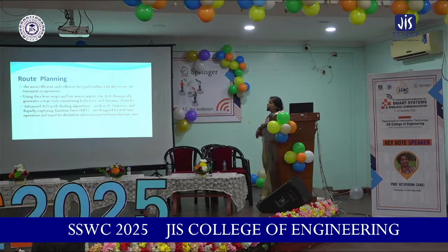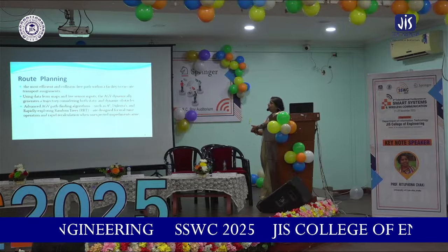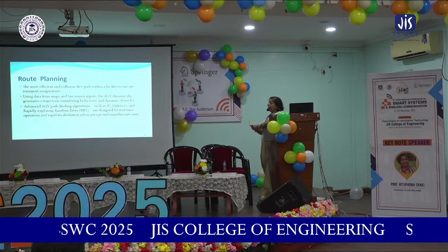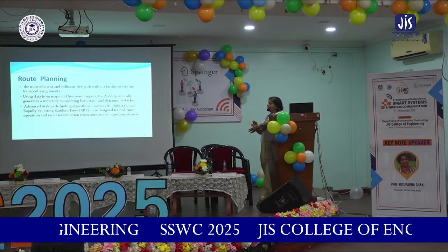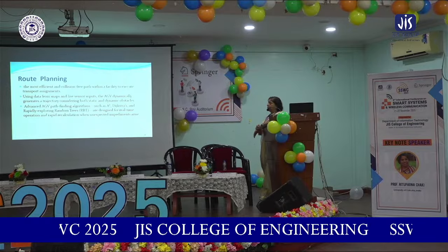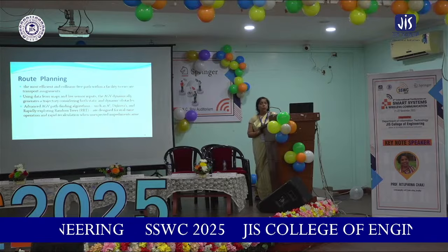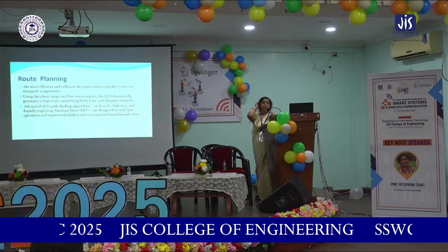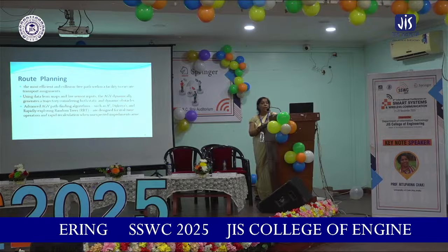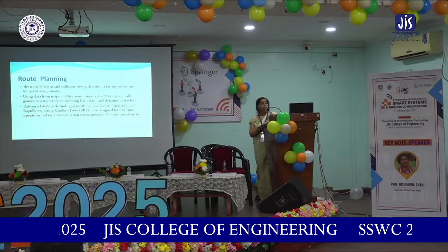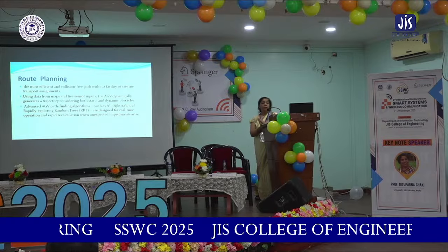Okay, so for route planning, we try to have the most efficient and collision-free path within a facility to execute any kind of transport assignments. That is, obviously, we are thinking of pathfinding algorithms, which are the A-star, Dijkstra's, and rapidly exploring random trees, and many more. When a robot is moving around you, it has to face some unplanned objects in its path. How does it face that object, how much does it have to back up, and how does it decide whether it goes right or left?